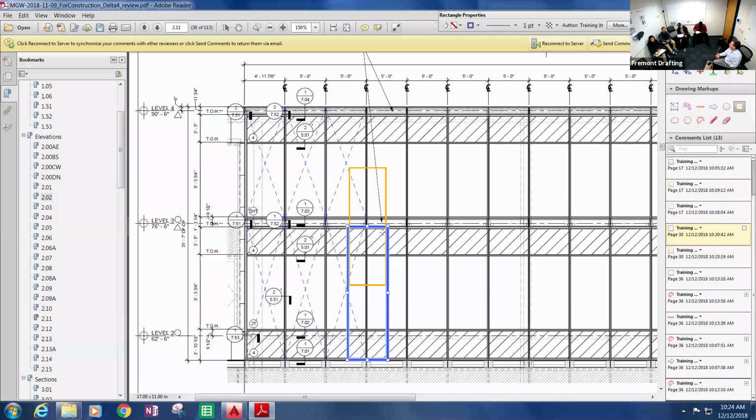So really, as we're looking at it pre-engineering wise, typically I'm getting a 5 foot by 14 foot, so I'm at 70 square feet times the wind load. And then I'm just applying that as dead load and wind load, even though it's offset. When you get to the bottoms and cantilevers and tops and parapet caps, you might have some larger tributary areas. But for the typical walls, it's really just the typical bay by the typical floor to floor, and it gives you what you need.